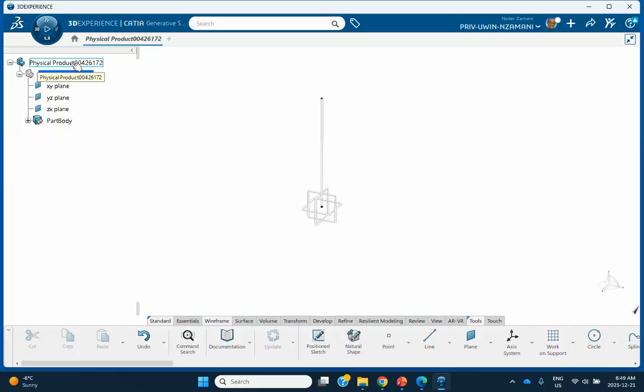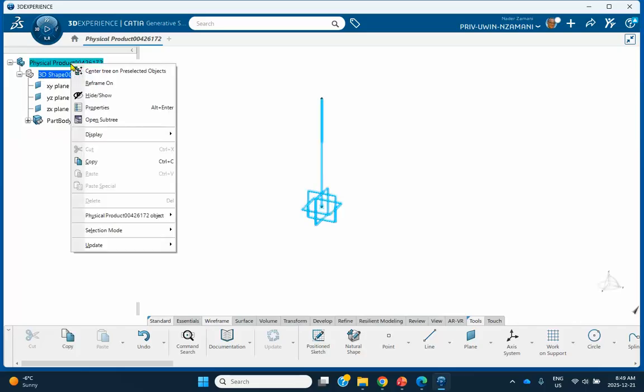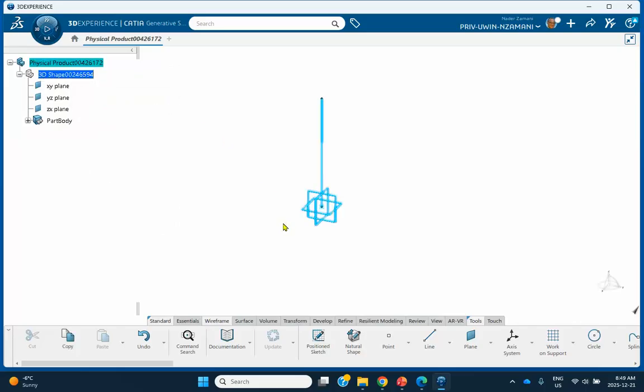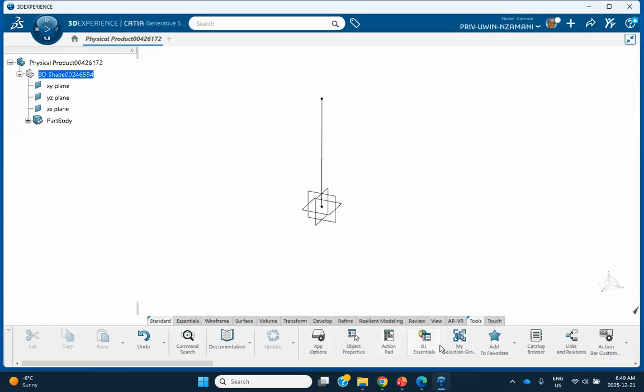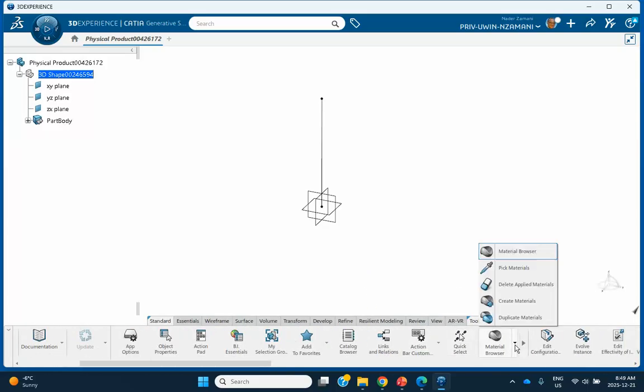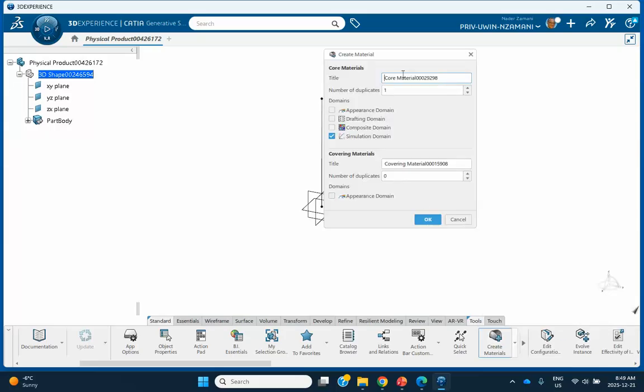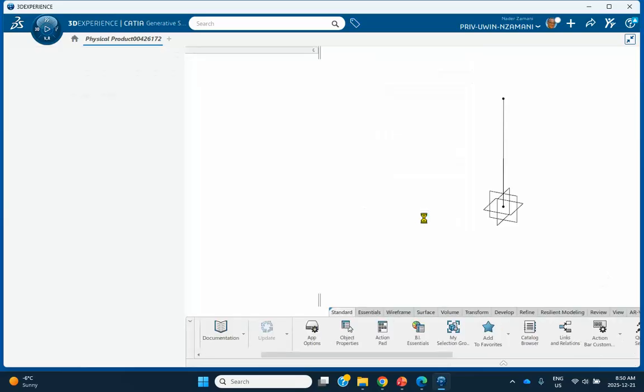Incidentally, let me change, well, that's okay. You can just leave it the way it is. Now, we're going to apply material properties. So you go to Tool, Create Material. This is going to be, you have to make sure the simulation is checked. For finite element, you need that. And then we say, okay.